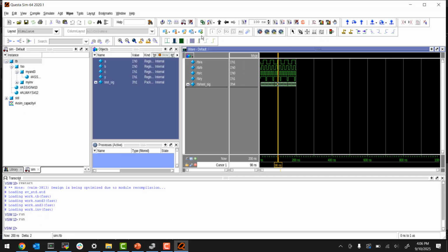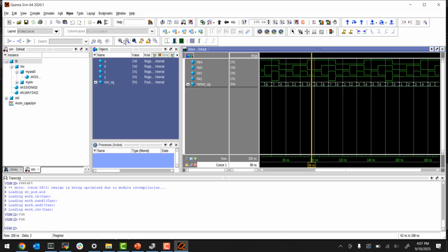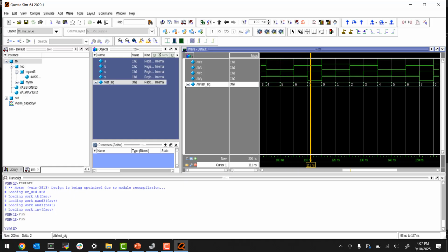So you can see that. I can also zoom in here, and you can see the waveform. By the way, I kind of brushed past this, but when I ran it, there's a button up here that advances the simulation. Every time you hit that, it runs for 100 nanoseconds. The nanoseconds is meaningless because there's no delay being modeled here. It could have been 100 picoseconds or 100 femtoseconds. It doesn't matter, it's just simulation.